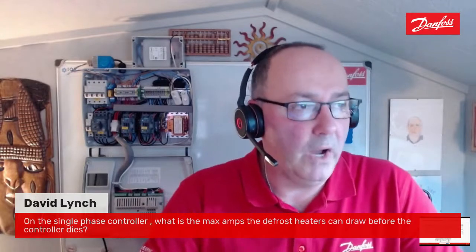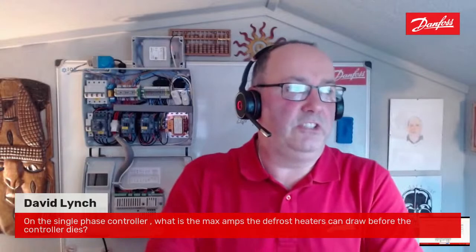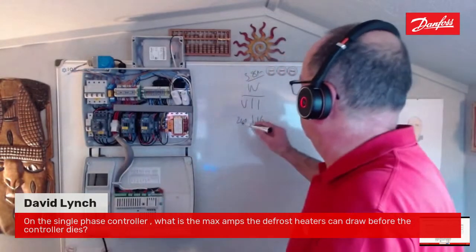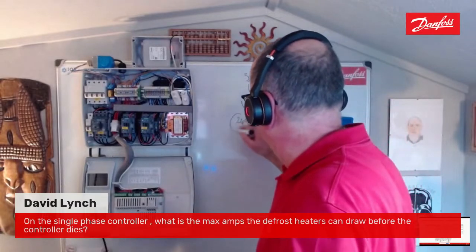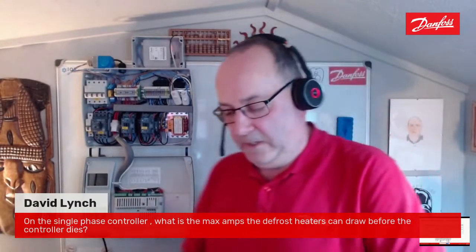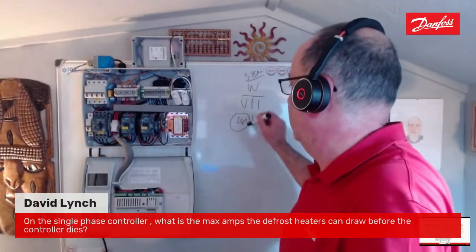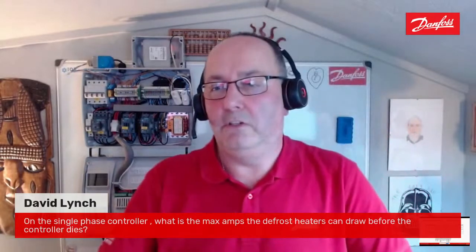But just be aware of that, because although the relay is rated at 30 amps, as it says on there, that's rated at AC1. Resistive load is a little bit different, so it's 16 amps. And I always say 240 because in the UK, if you put your meter on, we are pulling 240. I think the harmonized voltage now is 230, and it makes a little bit of a difference. But if you put a meter on, we're pulling 240.